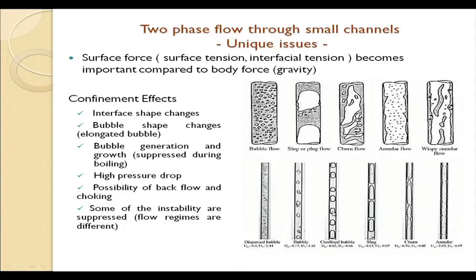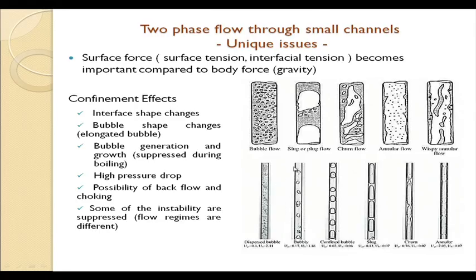So, how to differentiate them? Some people call it bubbly, some call it isolated bubbly, because there is very little chance of the bubbles coalescing, and in the other case they call them either coalescing bubbly or confined bubbly, because it appears as if the bubble has been compressed by the channel wall to take that particular shape and flow.